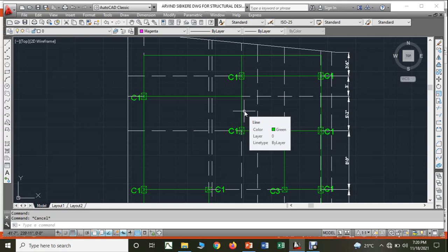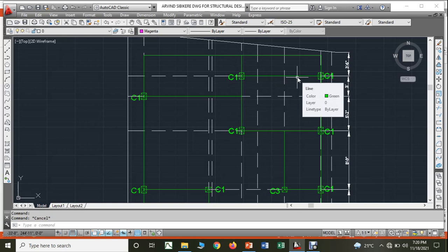And now I told you on what basis we can justify that a column is going to receive more loads. Now, if I take this column C1, you can see, student, that it is going to receive three beams, this one and this one, out of which this is a main beam, this is a main beam, and this is a cantilever projection.